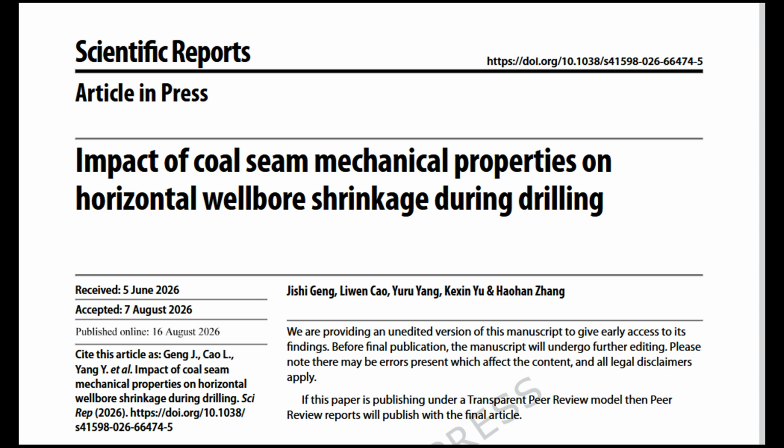Equation 2 is the equilibrium equation for a small element of rock in the radial direction. It expresses the balance between the change in radial stress with distance from the hole and the difference between the tangential and radial stresses. This is a fundamental static balance. The stress gradient must counteract the hoop stress to keep the element in equilibrium.